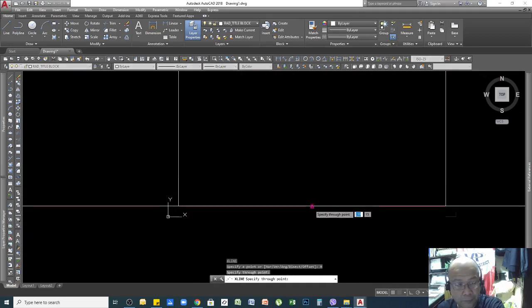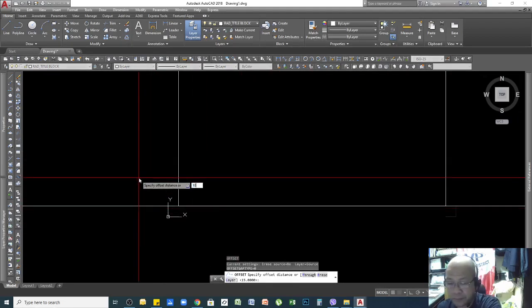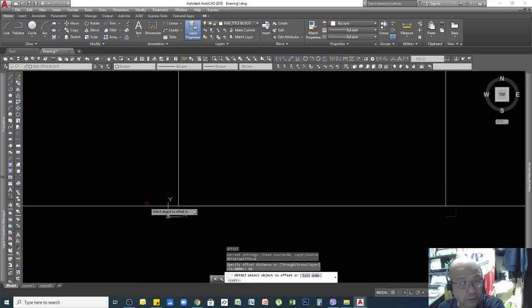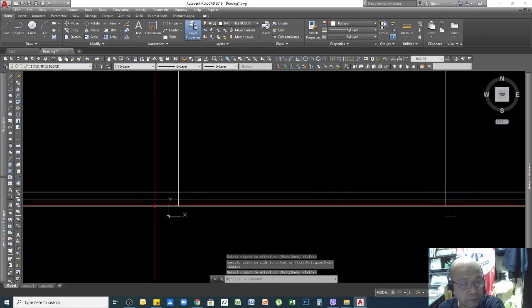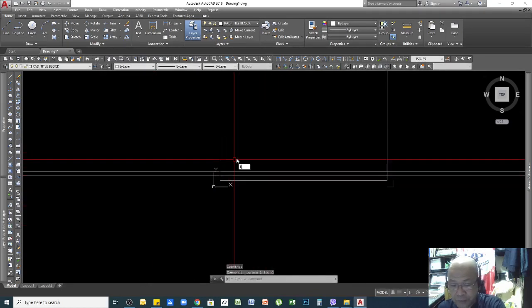I will put one line here, and then use offset. Just follow. I will do it a little bit faster so that at least the video will not be too long for you to watch. So 10, enter, enter. So that is your lines, and then divisions.